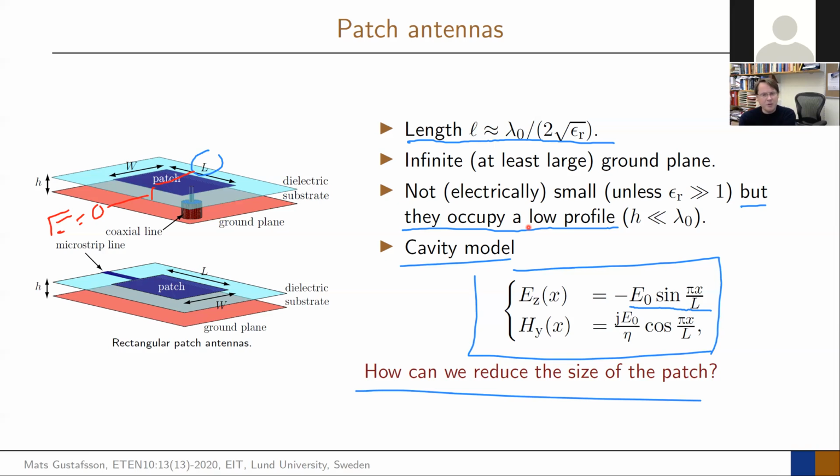That really means I can put a metal wall there. So what you can do in the center of these ones is that you can actually put a metal wall here. It doesn't change the cavity model because the electric field is still 0 on that metallic piece that sits there. So here I put a metallic wall. And if I put a metallic wall here, I have a feed on this side. That means delete what sits on the back side.